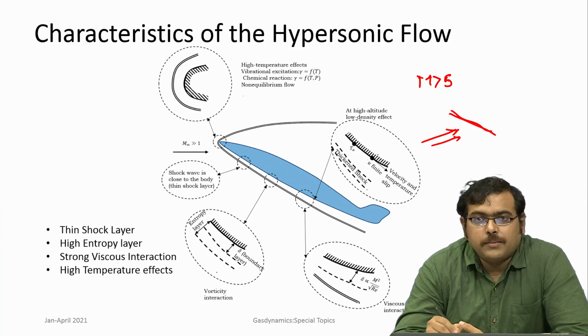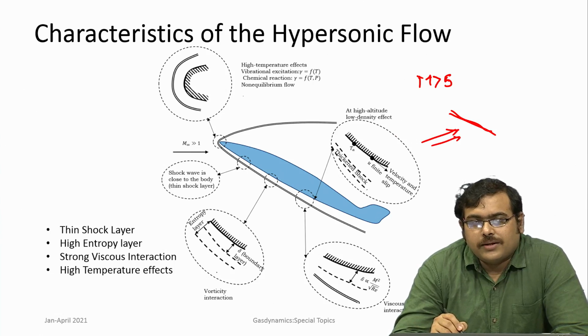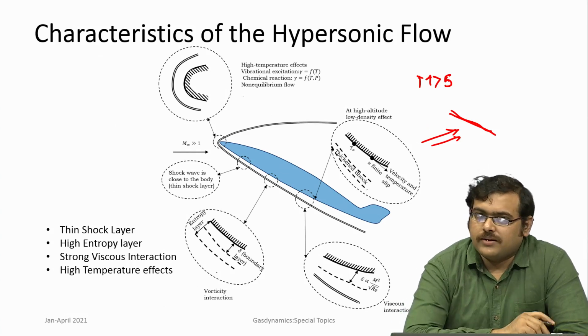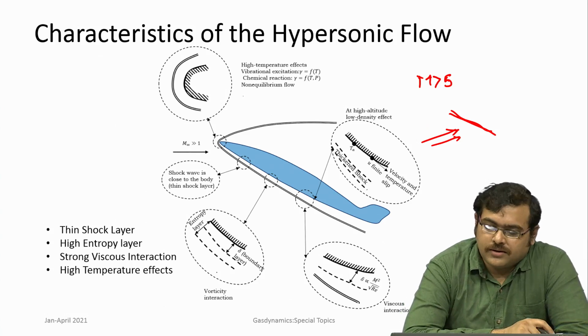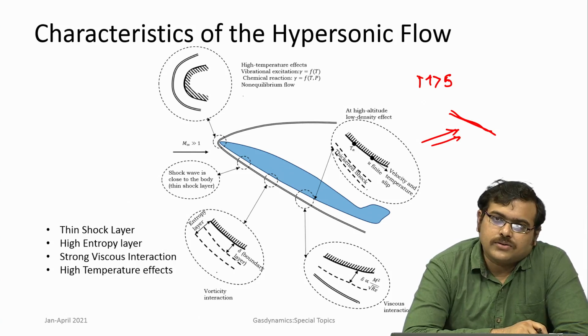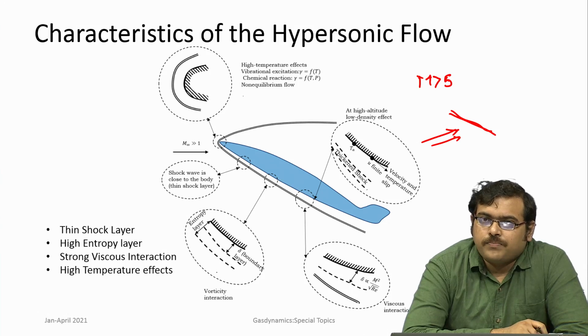Okay, so that is an impact method, also called the Newtonian method, and surprisingly in hypersonic flows these techniques, which are quite simple, work well. They are based only on the local inclination of the surface and nothing else. So, we will see some of these simple methods to look at hypersonic flow in the next class.